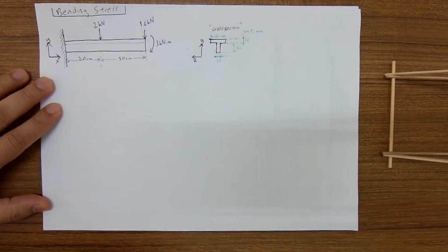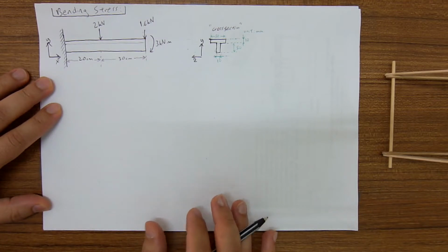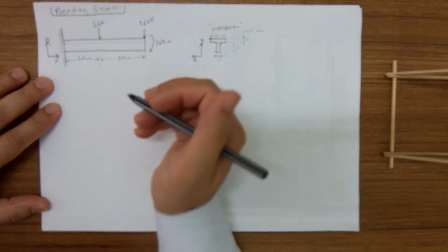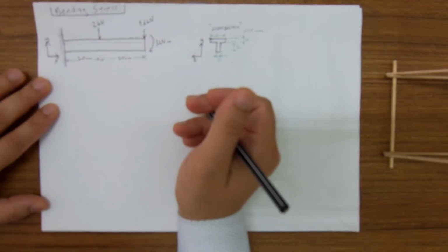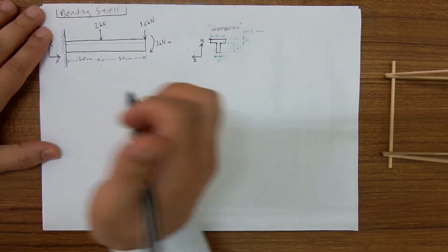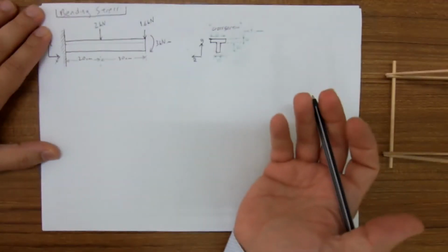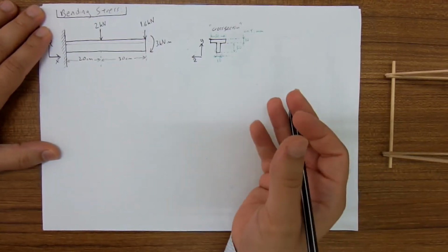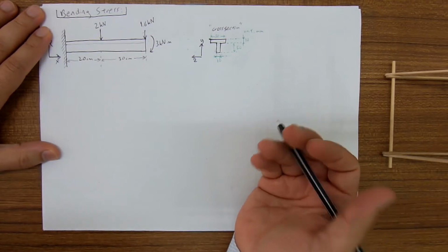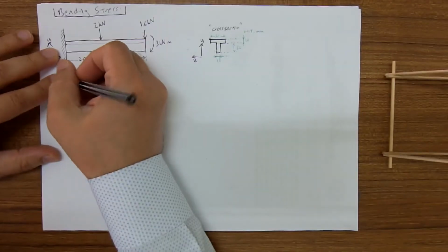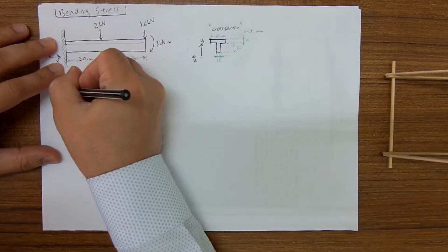And you remember from the shear moment diagrams, we first start with the global free body diagram of the beam, and then we draw a shear diagram and then moment diagram. On the moment diagram we can see the maximum moment. Let's draw the global free body diagram first.